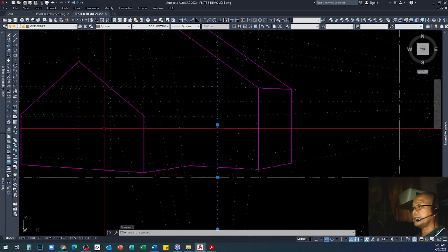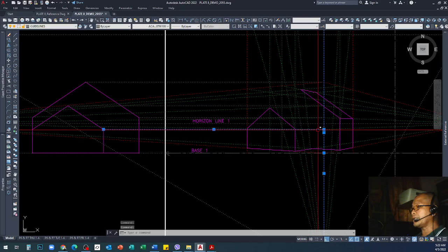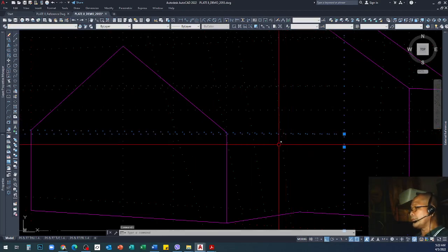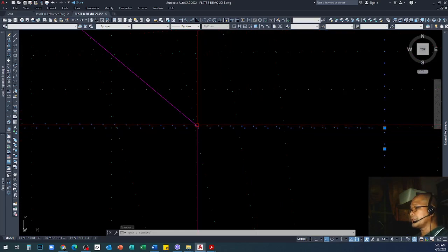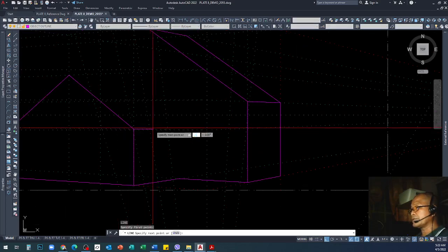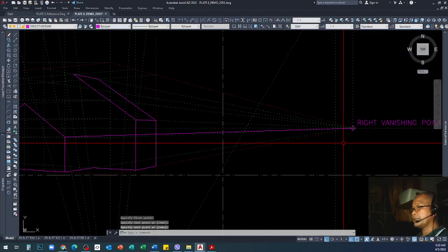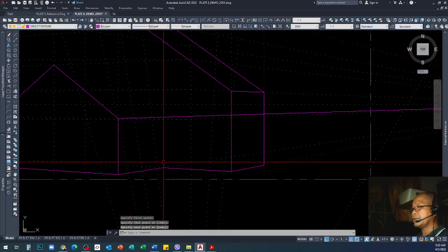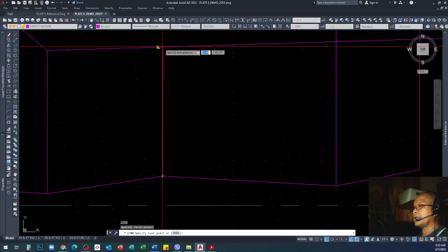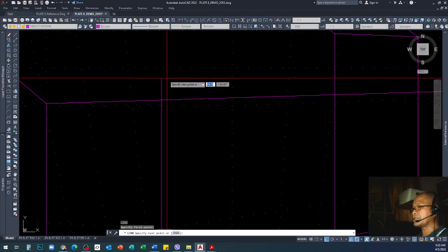The height of that, I already pointed out to you earlier, and we projected it to the left vanishing point using this line, where it falls on this corner already. So use that line to project a line to your right vanishing point. Alright, and that is your guide. So all you need to do is draw a vertical line overlapping that one, and then you can just trim.